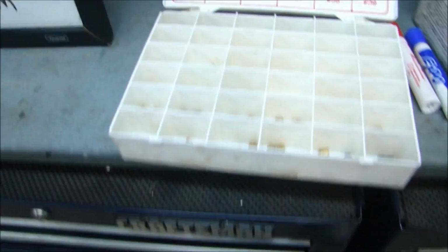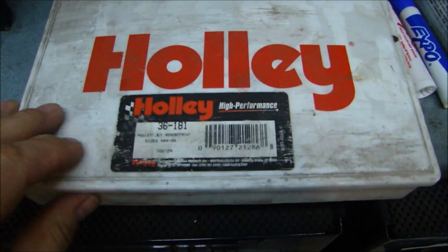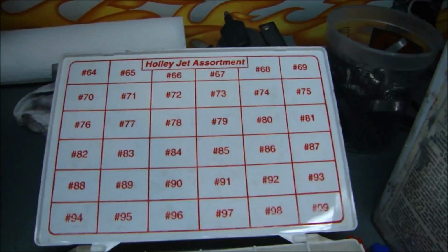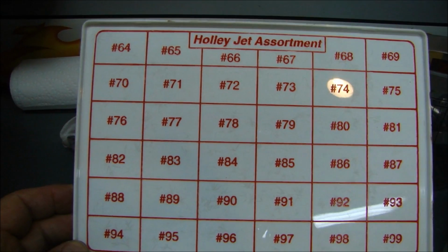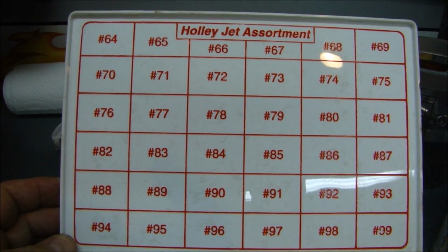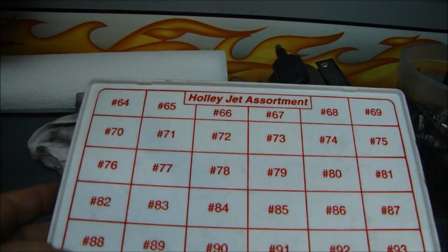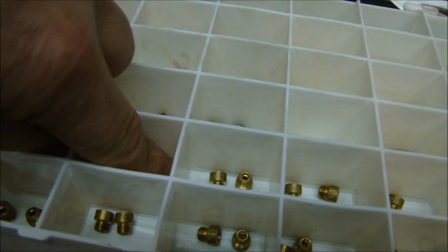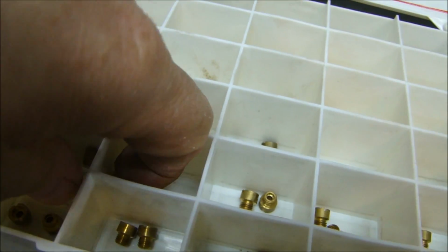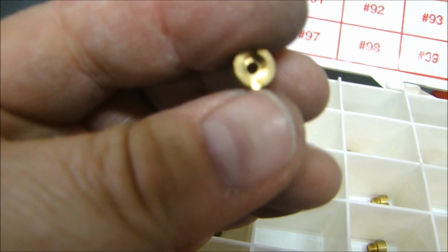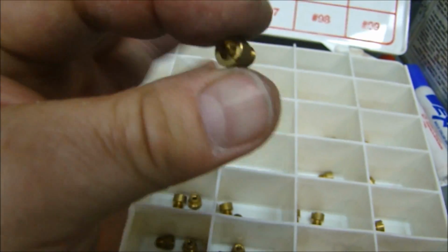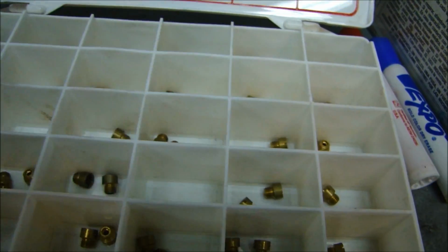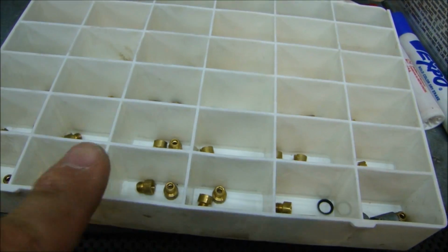Now, inside, let me just show you this real quick. When you look inside your carburetor, you have the jets, and this is one of the jet assortments that I use. These are the jet sizes, and you can change the jets inside the carburetor. They're by number, they change by thousandths, and you can see here it goes 64, 65, 66, different sizes for the jet. You change them in pairs, so you have the left and right, but the jet is where the fuel comes out and gets atomized as it goes through the metering rod. You don't want to mix them up.